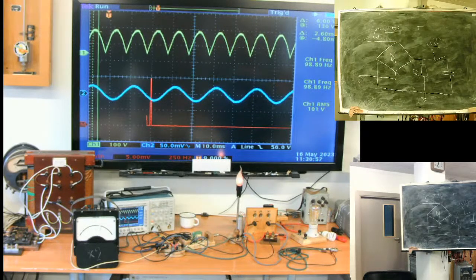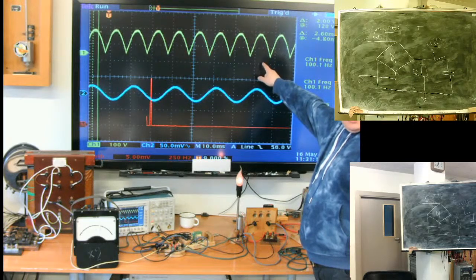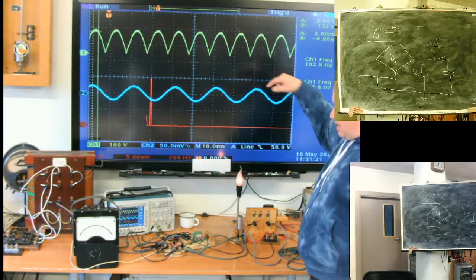If the current is positive, it gets to the same point, and if it's negative, it also gets to the same point, because of the disposition of the diodes. In one half, the first and third diodes work on the positive waves; on negative waves, the second and fourth work. This corresponds, this voltage, to this theory. Nice.